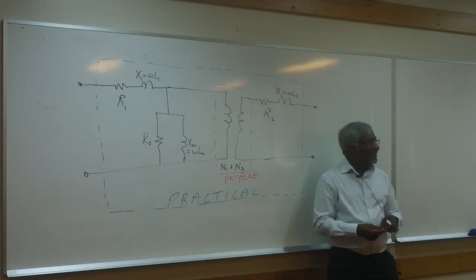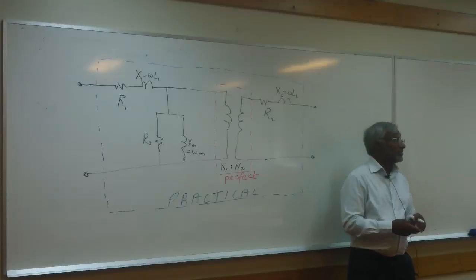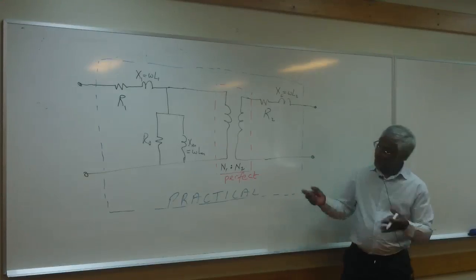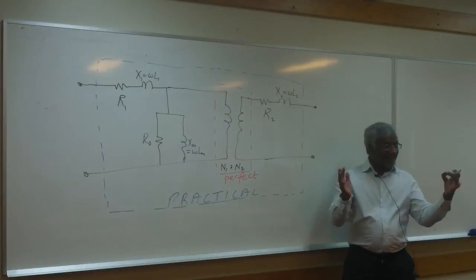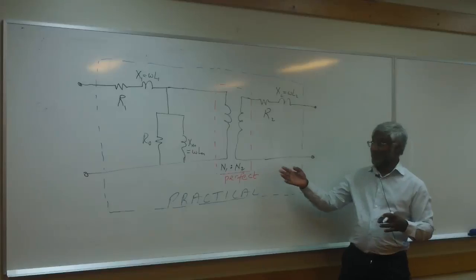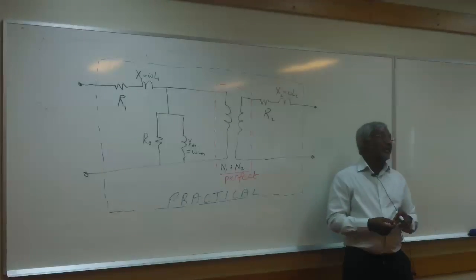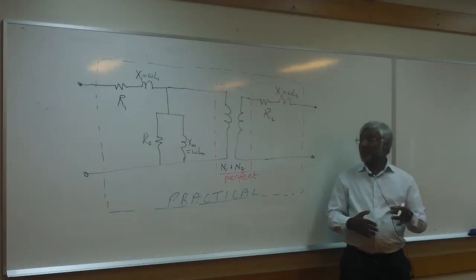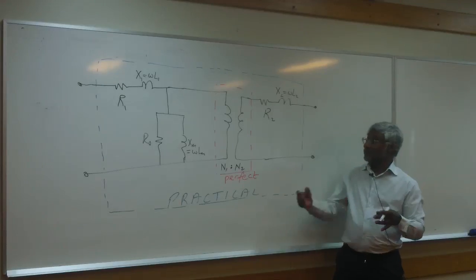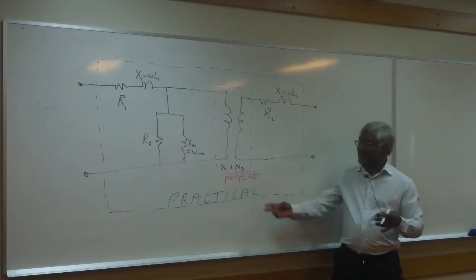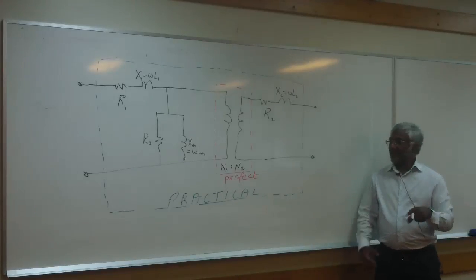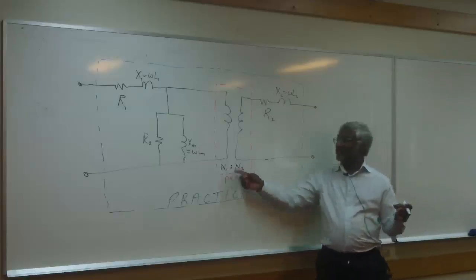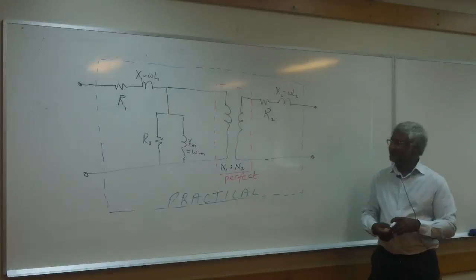About a month ago, I was in a 275 kV to 132 kV substation, and I took some photos of the transformer there. Plenty of information on the nameplate, and one piece of information is definitely the voltage ratio, of course. From the nominal voltage ratio, you can work out the nominal turns ratio. That's something you get off the nameplate if the transformer already exists, or if you're building the transformer, then that's something you would decide yourself.